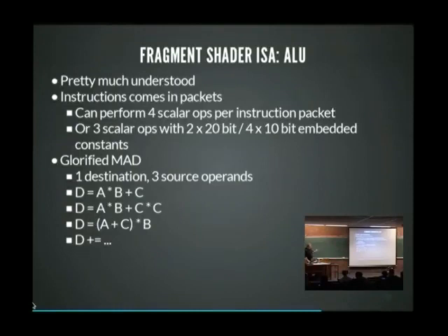And when it does that, it uses some kind of special accumulation register, it seems. It also has min, max, and conditional select. My understanding so far is that if you change the MAD to min, you still get the C stuff, so it still tries to add C. You just pass 0 in for C instead, so it's no problem.